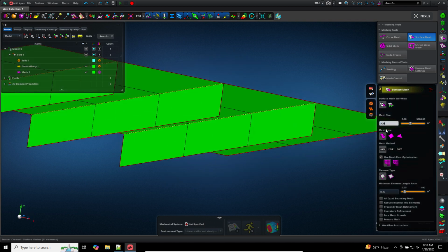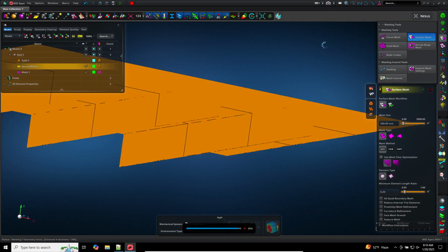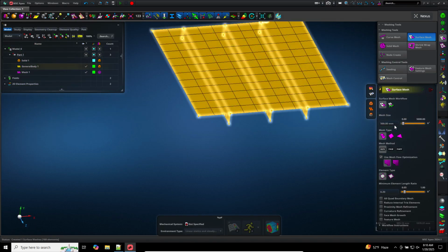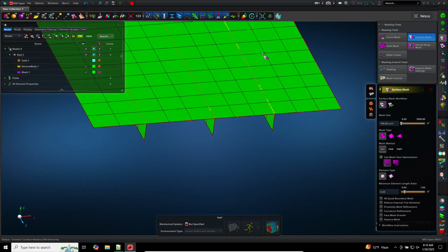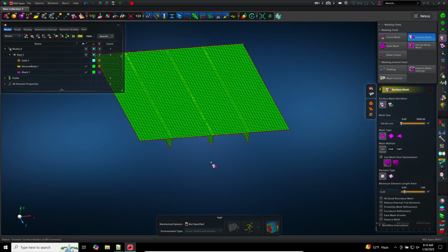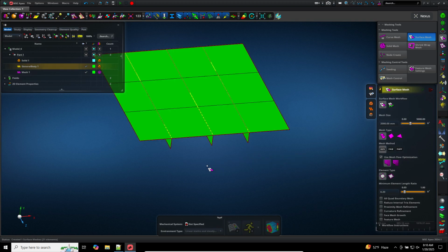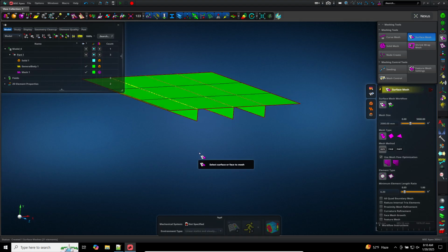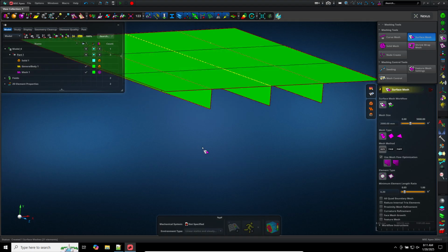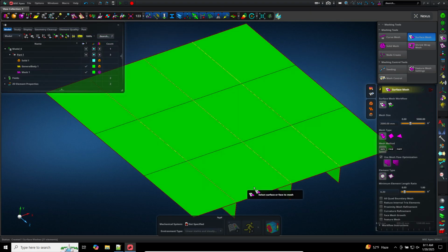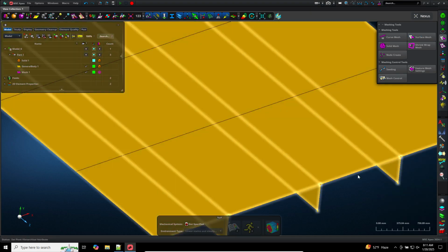You don't want to do this right off the bat. I say this for the following reasons. This is still modestly small, so let's go ahead and use 100 millimeters. You don't want to jump straight to a mesh like this. If you're new, it's better to use a very large element size like this. The reason is because you want to get a handle. You want to get used to various other operations before you jump to a very small element size mesh. So here, let's work with this. Let's go ahead and close this.